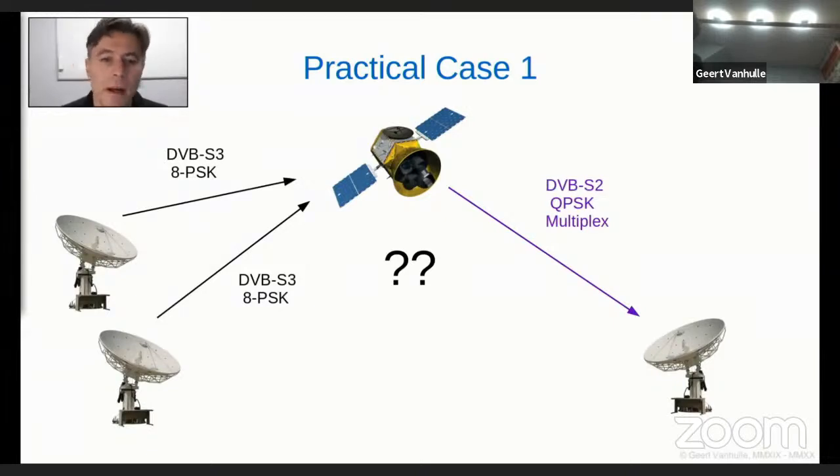We can go from QPSK up to 8PSK, again increasing the amount of data that we can squeeze into the same bandwidth. So the customer can use the same transponder, putting up 2 slots next to each other, but then there's a problem. The satellite doesn't do any processing.